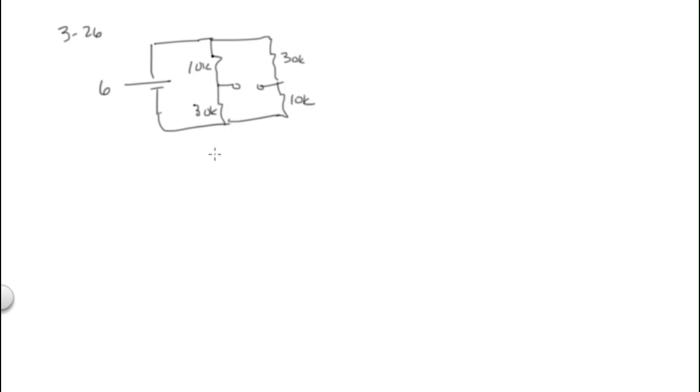So this resistance here was, okay, the voltage VAB was 3 volts. It was 4.5 minus 1.5, and my R Thevenin was 15K. It was 30 in parallel with 10 plus 30 in parallel with 10, or 7.5 plus 7.5.